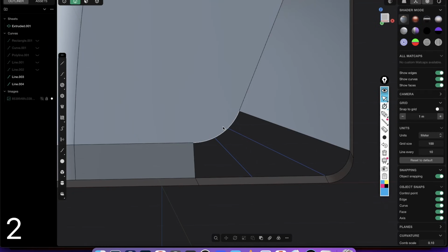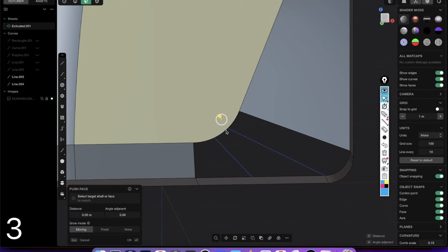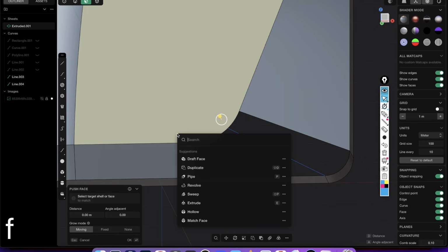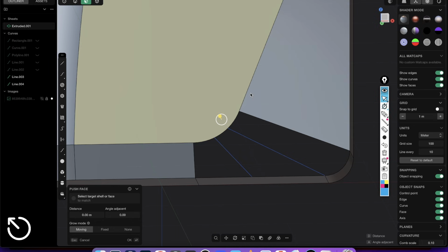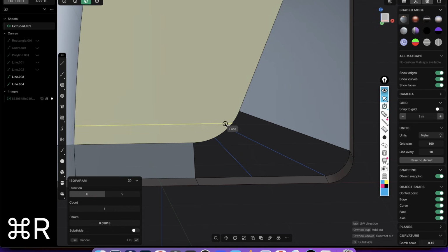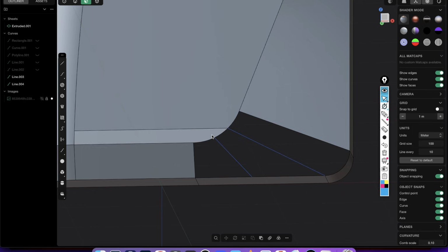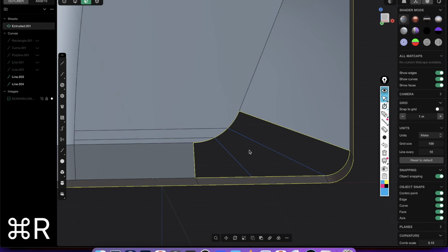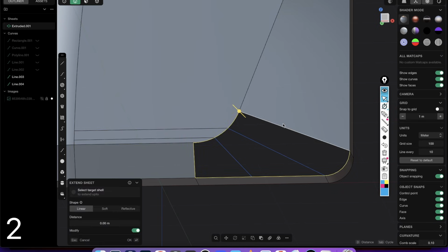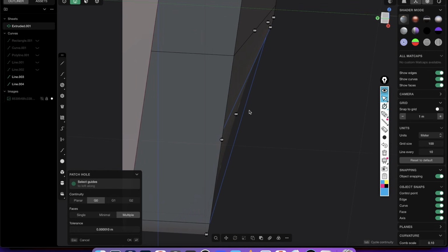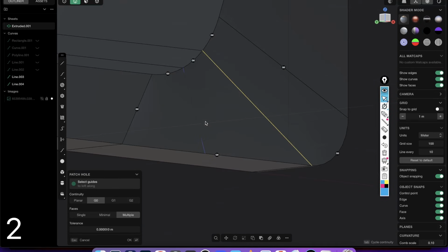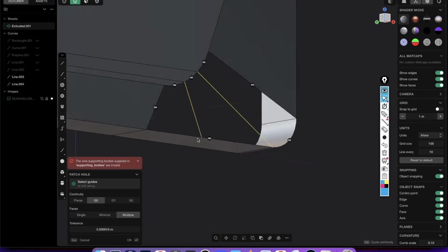And again, don't forget to add, so break this edge here. Again, isoparam, so just put it on Shift or Control R or whatever. So you just select this face, Control R, bam, isoparam, you can add a line, bam, you select this face, Control R, isoparam, you can snap it, and if you press 2, Alt click, patch it, you see here, the face that is created from the patch is very much not straight, but if you press Shift click, bam, it instantly snaps to this curve, and bam, snaps to this curve.